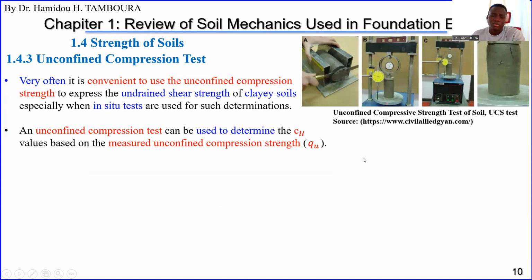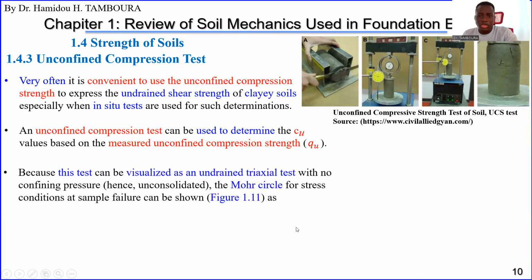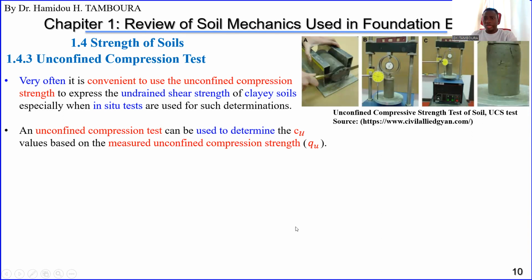This test can be used to determine the CU. Do you remember what CU is? From the previous slide, the undrained cohesion, which is at the same time the undrained shear strength. We can use this test to obtain the CU by measuring the unconfined compression strength, QU, from the load applied on the sample.